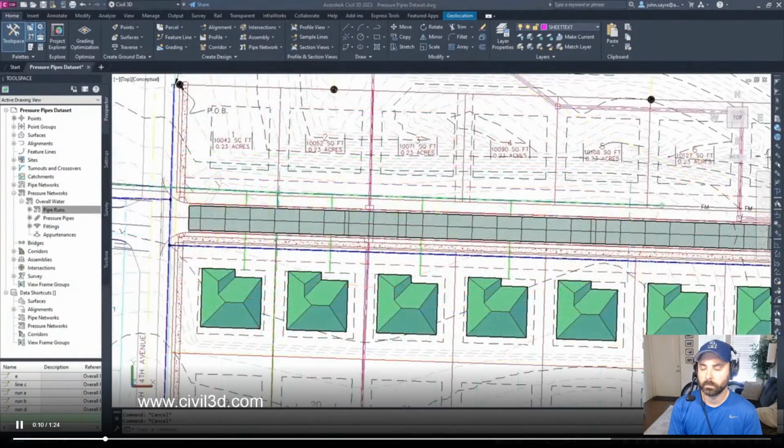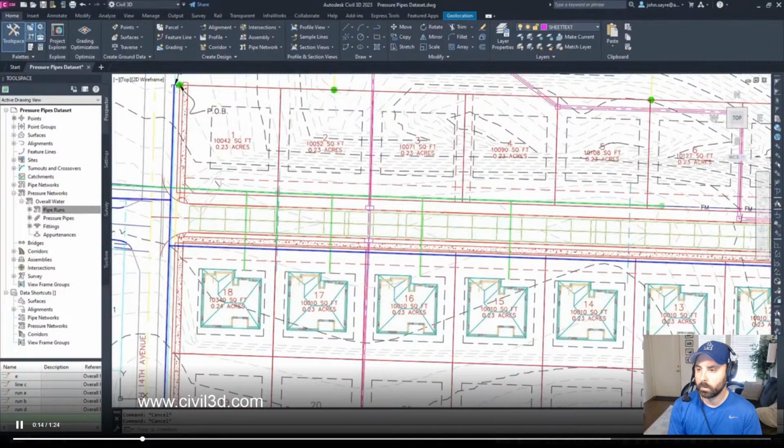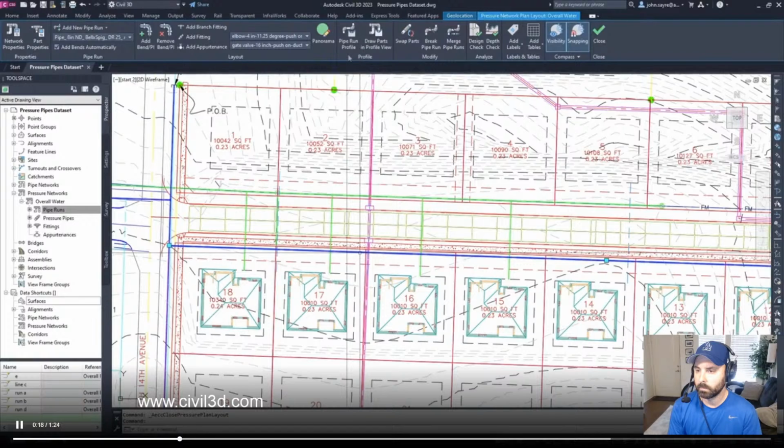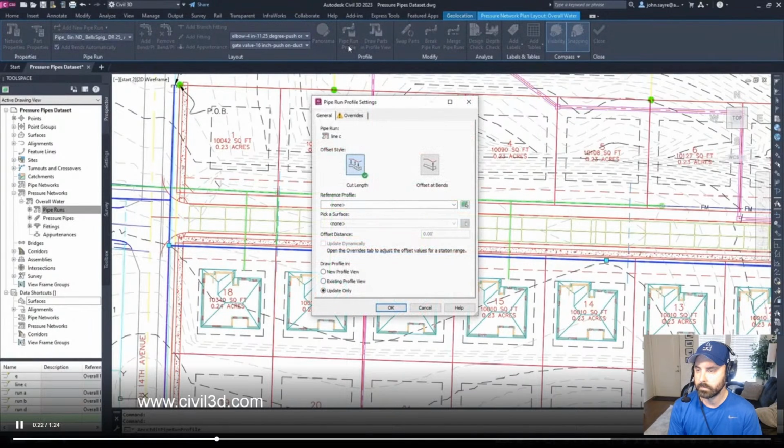This introduces enhancements to pressure pipe profiles when encountering pipe crossings or interference that require creating a lowering. This example focuses on the design of a water main. You can see the water main will cross paths with several utilities here. Sanitary sewer, stormwater, oh, that's useful. Sanitary sewer service laterals will need to be taken into consideration.